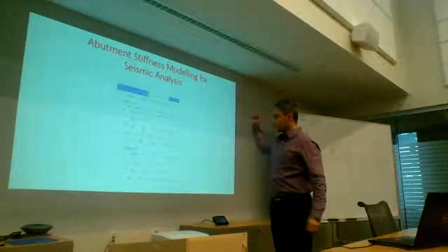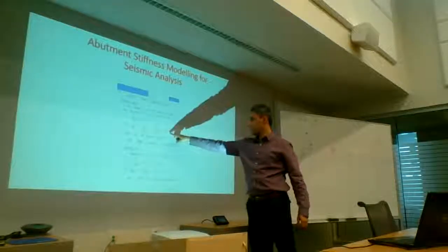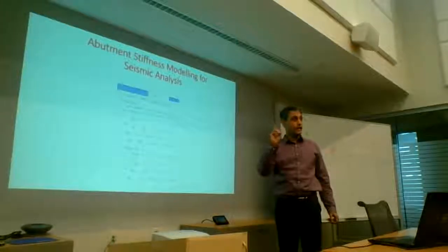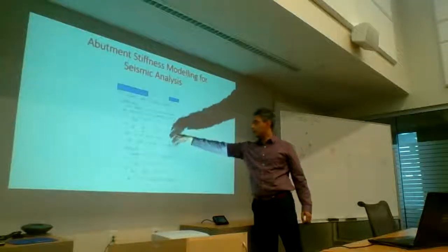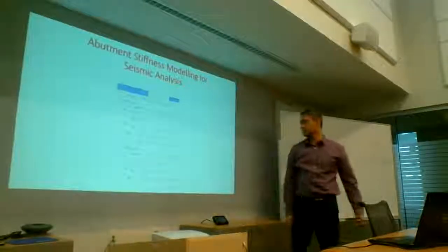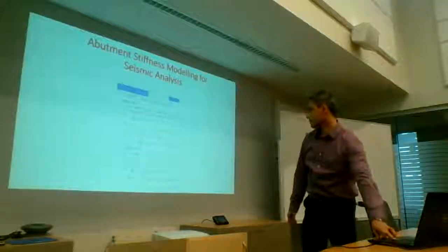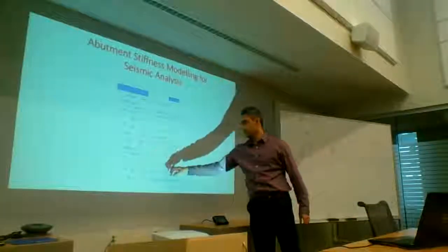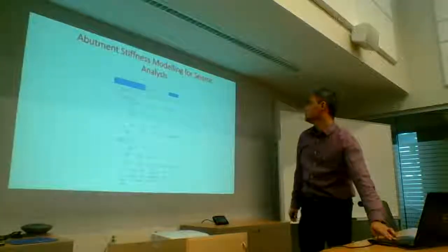So we take the displacement from there, we take the plateau force, we come up with a new stiffness. Now all of a sudden, my stiffness has dropped from 190 something odd thousand, or half of that, to 28,000 or 14,000. And now I come up with the same thing again, and I find that my next displacement is 117 mils, which is much larger than 55 mils, over a factor of 2.